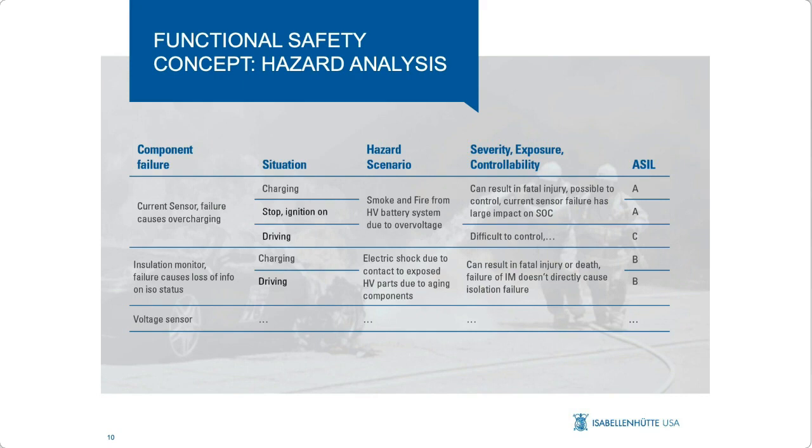A failure of the current sensor, for instance, can cause overcharging of the battery. This situation can occur during charging, while the vehicle is in stop but with the ignition on, or during driving in recuperation mode. The resulting hazard here is smoke and fire from the high voltage battery system due to overvoltage.